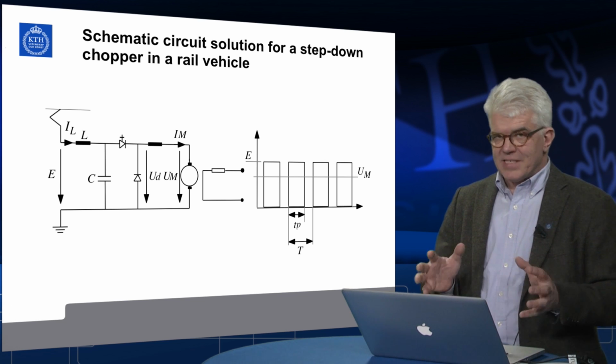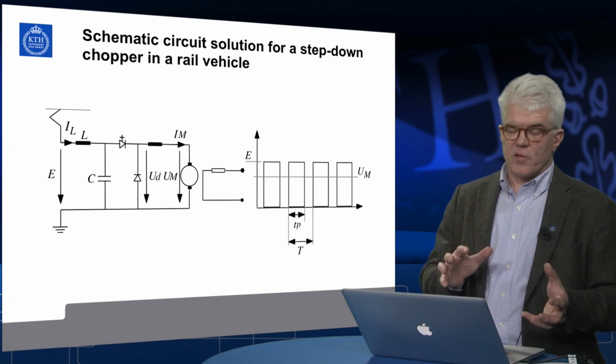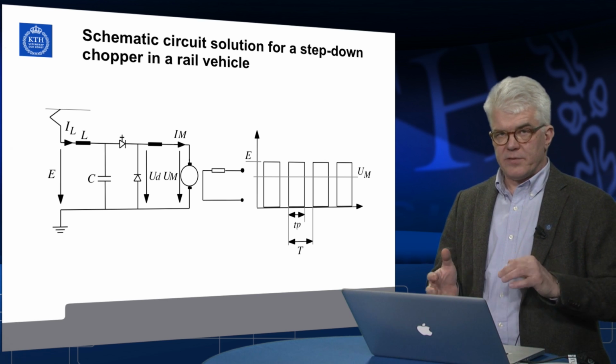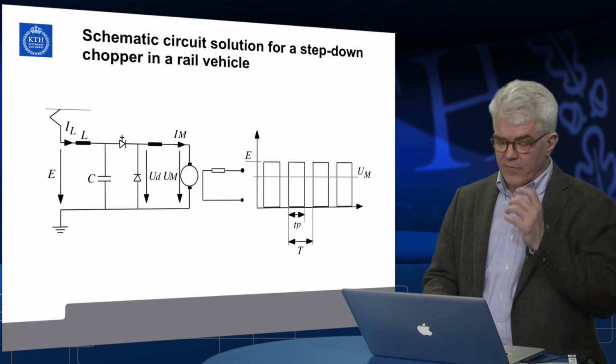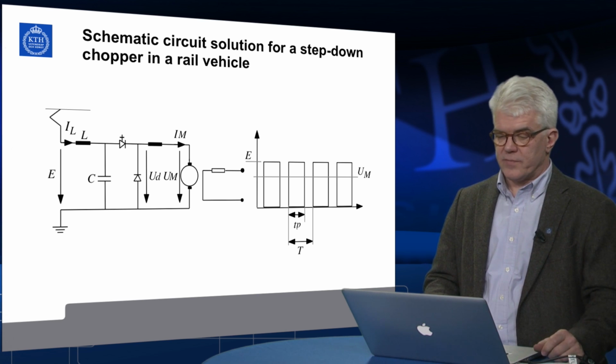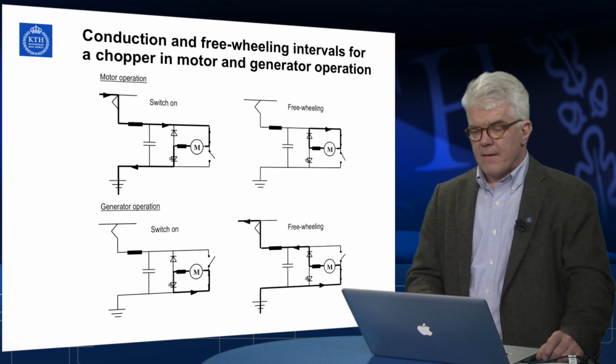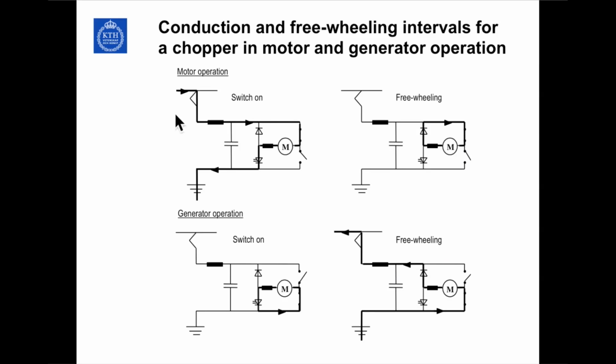So principally, the DC motor is controlled by controlling the voltage amplitude, and the AC motor is controlled by controlling the frequency of the voltage supplied or applied to the motor. In this case, you can see 4 distinct operational modes.